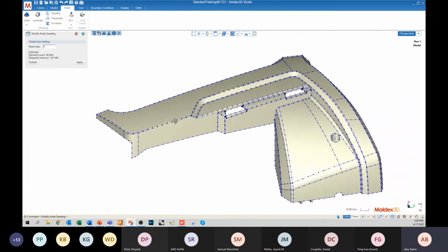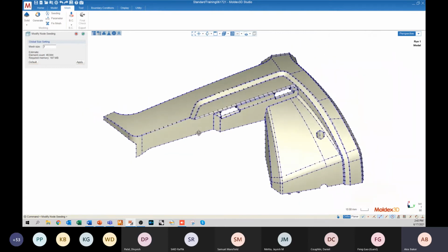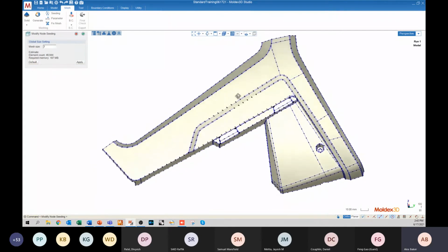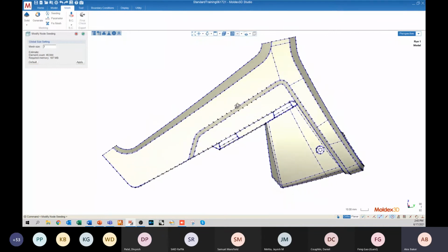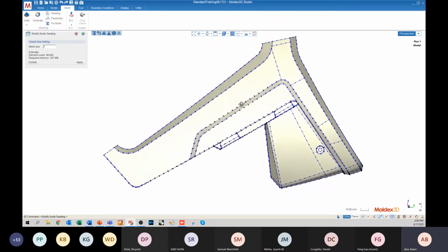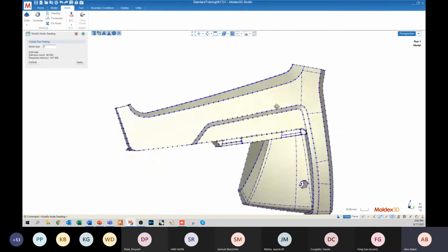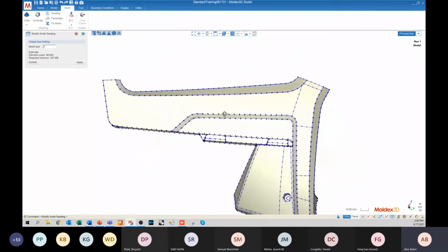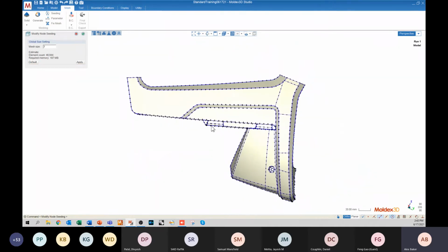All right, and to arrive at this trade-off or this optimal point, we're going to use what's called the Goldilocks method. The Goldilocks method dictates that we need to be looking down on the top of the part from the parting direction. So you're going to rotate your part around so that you're looking down the top of it. And then you're going to rotate the part around so that the longest dimension is horizontal on your screen.